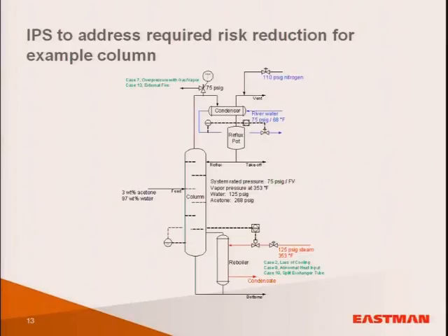And then we had an appropriately sized relief device that handled the other cases, overpressure with gas vapor and external fire. And we were able to use fire-resistant insulation to reduce the size of that relief system for the external fire scenario.